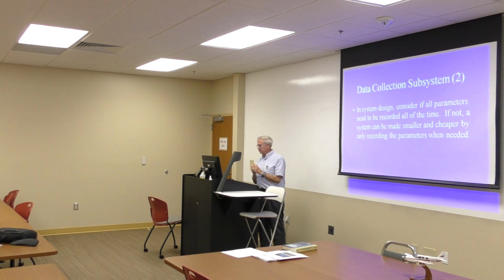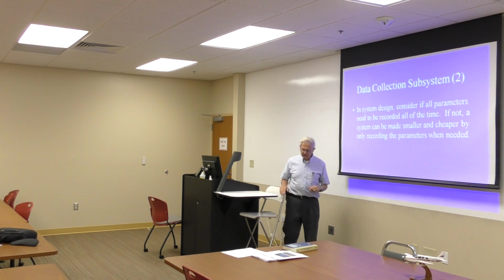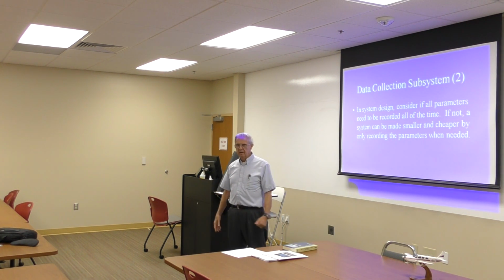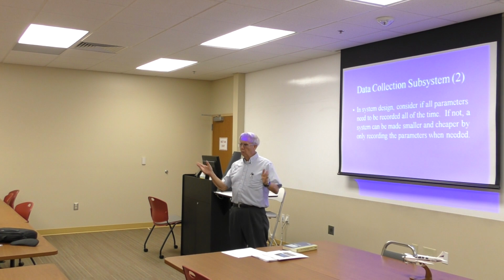For that data collection subsystem, consider if all the parameters need to be recorded all of the time. One of the things that the military flight test centers do, which I have complained about, is that they will take an airplane in and they instrument everything in sight. You don't need to do that. I mean, if you're only testing a specific thing, just instrument for that. But when you go to them and say, why are you doing all this? Oh, well, we might have an accident.